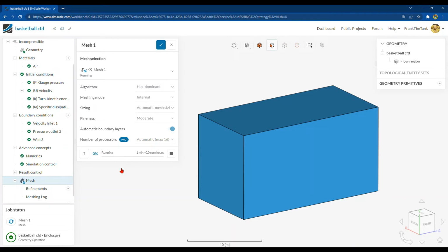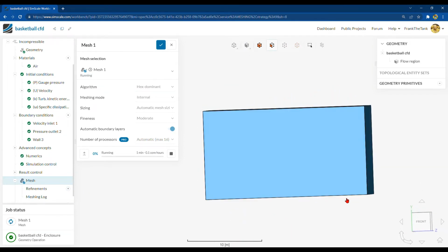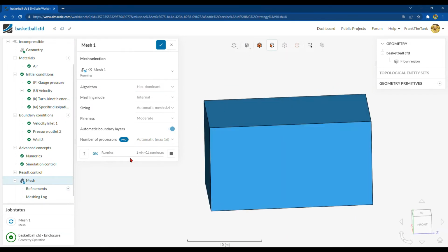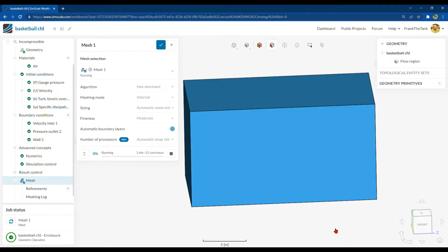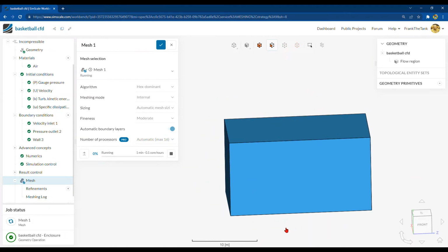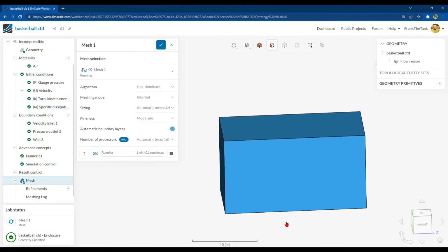I was going to say, the refinements, although I didn't do any right now, would be like adding more. Once the mesh is done running, you're going to see these tiny little boxes. The simulation checks the force on each of those boxes, adds them all together, and finds your solutions. So refinements make more of the boxes, and so you have finer solutions, I guess.